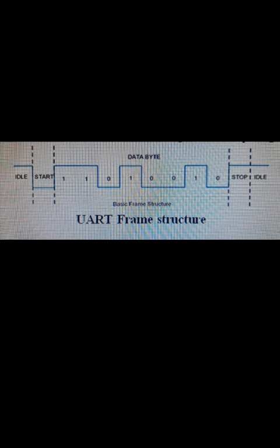Asynchronous serial communication is widely used for byte-oriented transmission. In asynchronous serial communication, a byte of data is transferred at a time. The UART serial communication protocol uses a defined frame structure for the data bytes, and that frame structure of the asynchronous communication consists of the following.